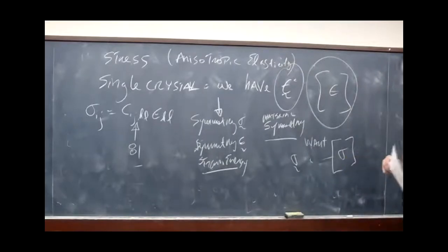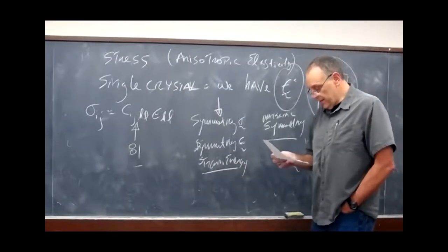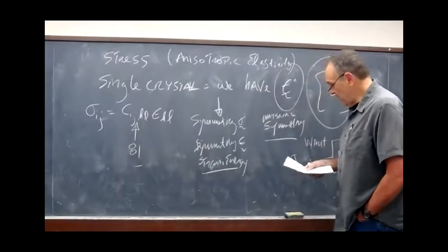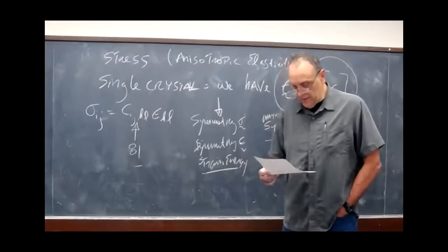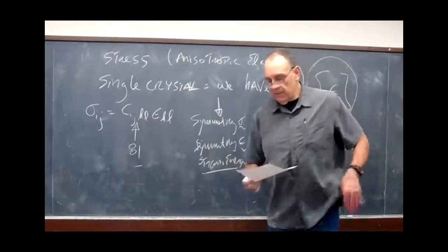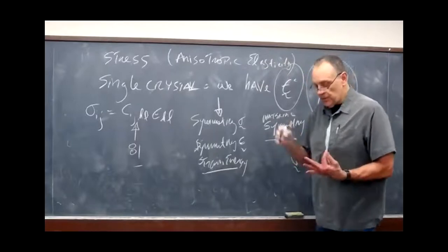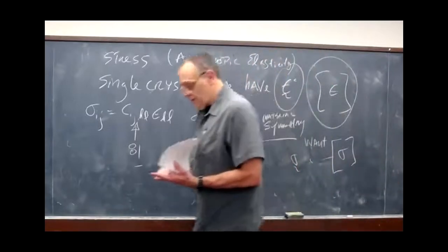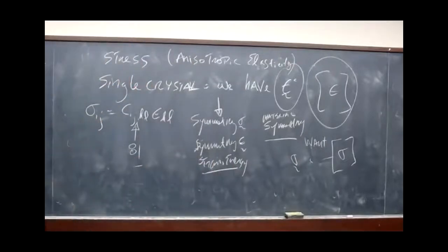And in the world of metals, we get really lucky because our materials are pretty symmetric. So we often have a lot of cubics, and we do some hexagonal close pack. But the machinery of crystallography obviously works for something with a lot less symmetry, and the machinery of anisotropic elasticity also works the same way. The hard part sometimes is getting those elastic constants.